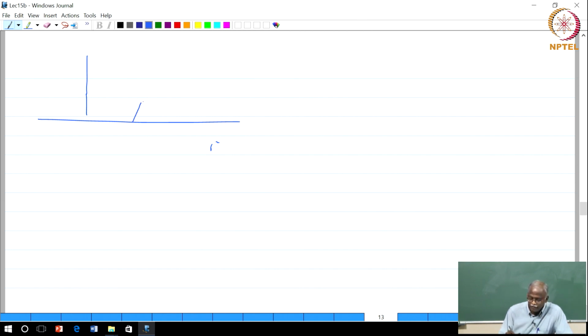If I have a signal whose response looks like this, from omega naught to omega naught plus 2 pi over m, between 0 and 2 pi, a spectrum of this type says it is a complex band pass signal which contains frequencies from omega naught to omega naught plus 2 pi over m.